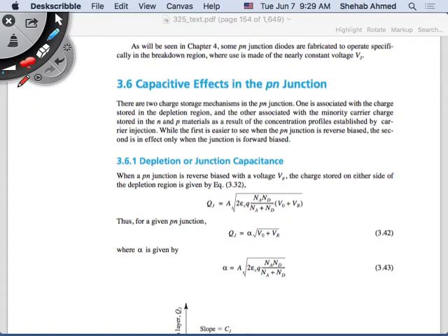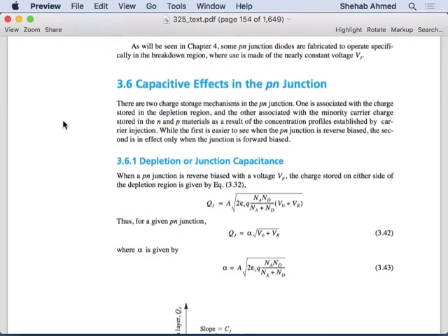So you can model this change in the amount of charge in the depletion layer and the change in the amount of charge due to diffusion from both sides as capacitances, right? That's all this section means. I will skip this section basically. But all of this stuff takes time, right? So if you want to change from forward bias mode to reverse bias mode, what do you have to do? You remember, forward bias mode is when you've collapsed the depletion layer to as small as possible.